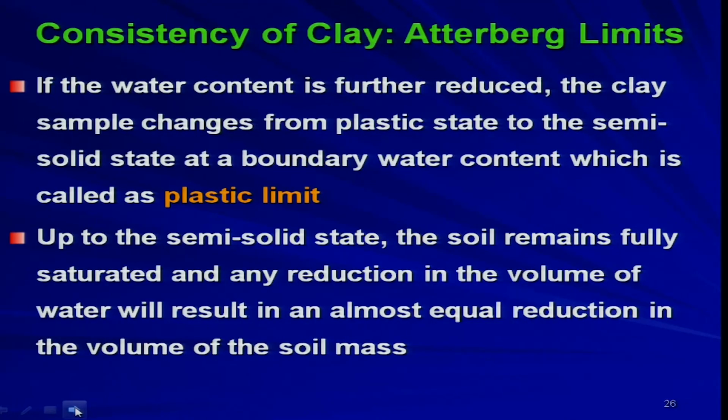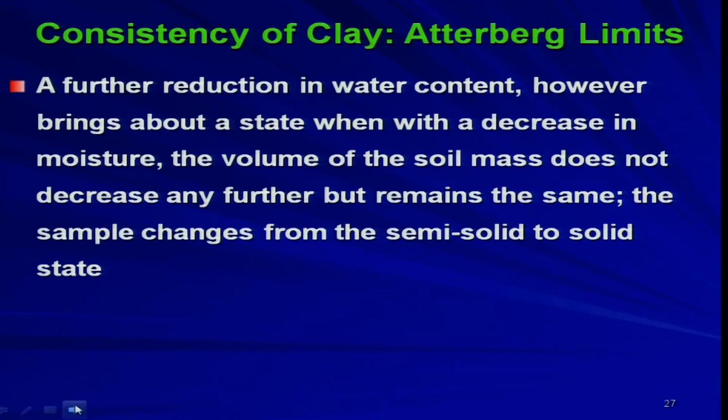So, that means from the plastic limit to liquid limit, the soil will be exhibiting the plastic state. Up to the semi-solid state, the soil remains fully saturated, and any reduction in the volume of water will result in an almost equal reduction in the volume of the soil mass. A further reduction in water content, however, brings about a state when, with a decrease in moisture, the volume of the soil mass does not decrease any further, but remains the same.